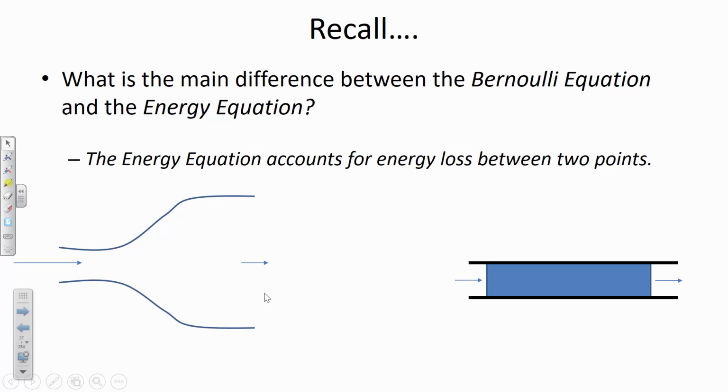And so those limitations about it being an inviscid fluid was all about the fact that Bernoulli's equation has no way to account for pipe friction and energy loss due to shear stress of the pipe resisting the movement of the water. So Bernoulli's equation is kind of blind to the fact that as the water flows from left to right, the pipe is pushing back against the water from the right towards the left. So we couldn't deal with that limitation. I mean, it's okay. Bernoulli's equation is okay as long as the 2 points you're applying it over are relatively close together, because 2 points that are close together won't experience much friction loss.